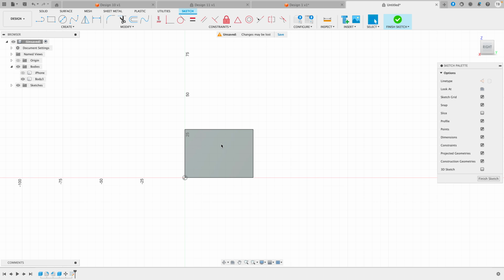And let's go ahead and create a custom sketch here, and I'll introduce you to a new thing as well, which is called constraints. So if we go up and create a line here, and if you drag your cursor over this line here, you'll notice a triangle appears right at the midpoint. And that means it's automatically going to create a midpoint constraint. So if we click here where the triangle is, and drag down, and let's go ahead and type a dimension as well. Let's do 18 and click.